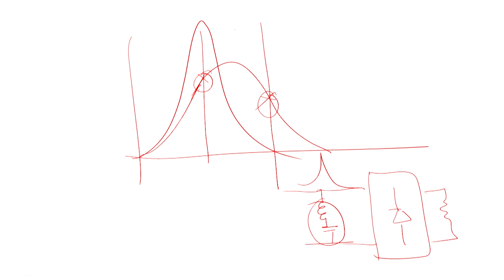So, here bandwidth can be more, of the 100 hertz, considering the 50 hertz system. This is a third harmonic 150 hertz and 250 hertz, and accordingly you can eliminate fifth and third, or if you have a problem only on the third, then you can take this kind of response and you can eliminate.